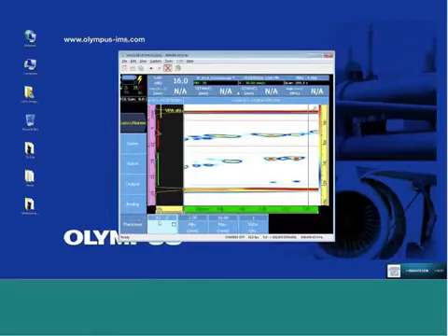It requires a source for the reading, and it requires a thickness range that we see here. The thickness range, and I'm looking at a 10 millimeter component. So naturally, the thickness on the high end is 10 millimeters. Thickness on the low end, we set at 2 millimeters. And normally you don't know this before the inspection. So we'll adjust this as necessary.